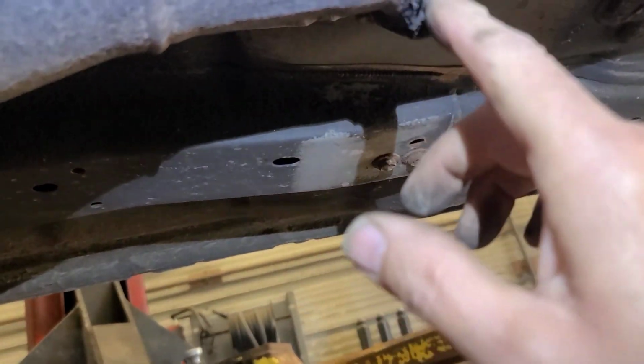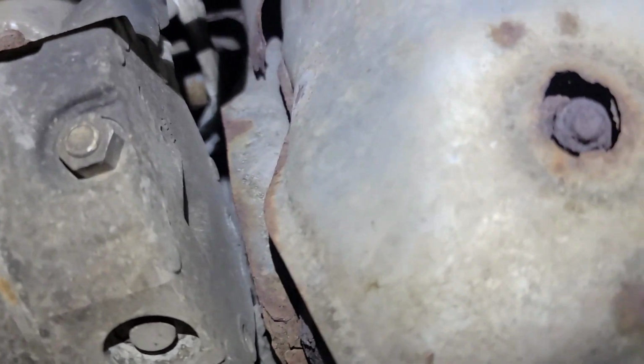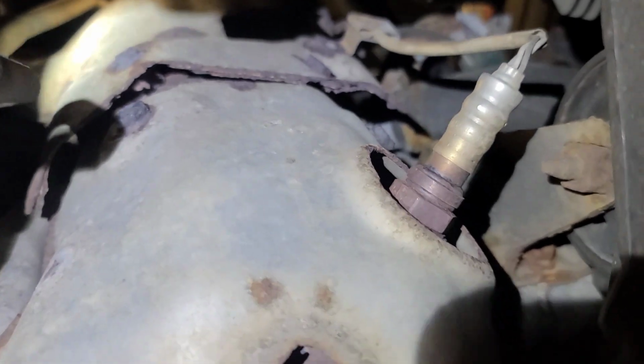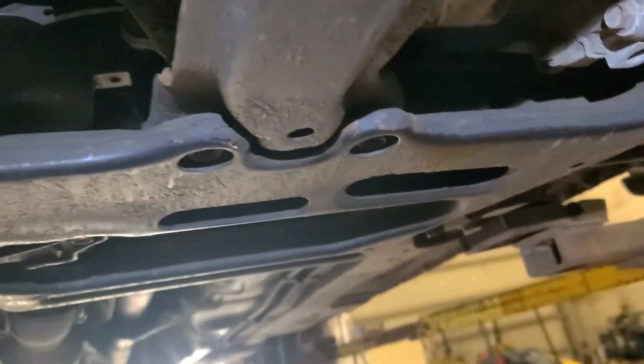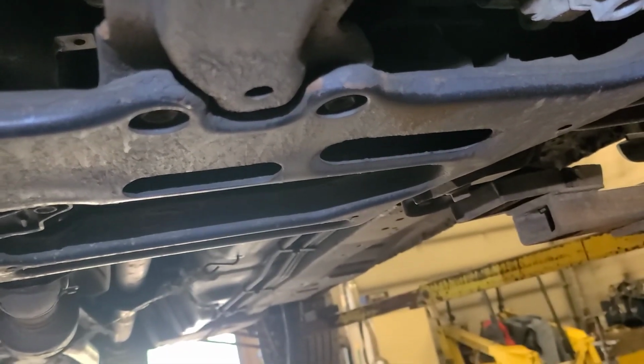Looking at the exhaust, it's been patched up many times. I get this custom hanger here. This is where the exhaust is leaking here by the looks of it. This flange is rusted out. But that shouldn't cause a catalyst efficiency code, because the catalytic converter is up here on the manifold. So there's the post-catalyst O2 sensor. But we're going to start it and confirm that there's no exhaust leaks at the catalytic converter. And then got to look at that vent or purge solenoid circuit.